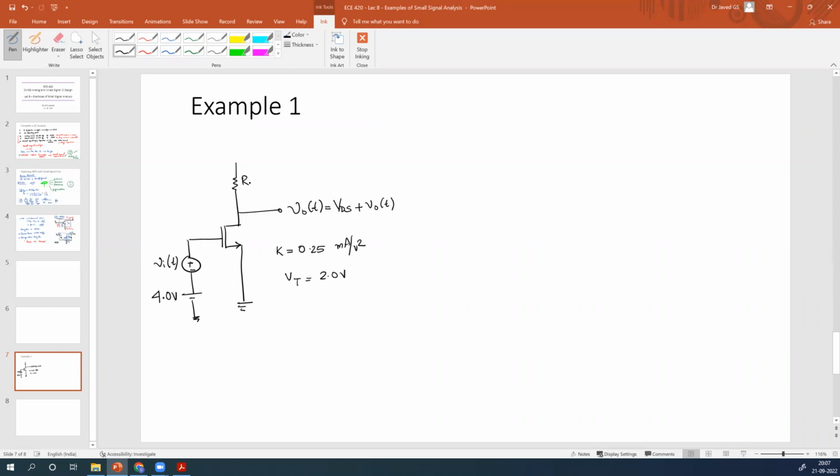What is RD that is given here? It is 5 kilo ohm. The current flowing through this drain, or through this resistor, is given as small i capital D of t, a time varying quantity, with I capital D plus i small d, again time varying. You now have the supply voltage given as 15 volt. Using 15 volt because it is a legacy design.